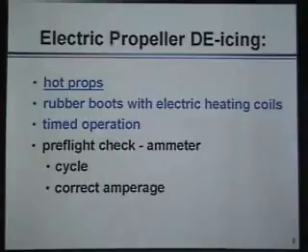If you're on the ground, even with the propeller spinning at idle, there's not nearly as much airflow across the propeller, and it's probably not nearly as cold. So it's very possible, or of course if you're doing this pre-flight check when the propellers aren't even spinning before you start the engines, it's going to be possible, in fact likely, that you're going to overheat. The wires are going to get too hot, the rubber boots are going to melt.